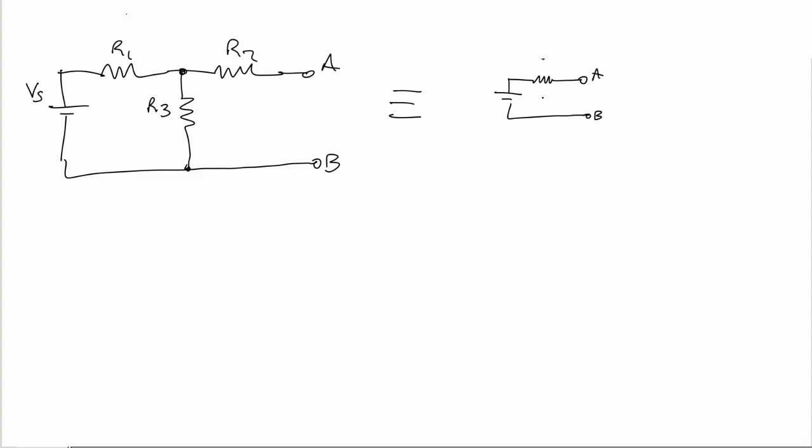What is this sort of arrangement known as? It's known as a Thevenin equivalent circuit. And this resistor, therefore, is known as RTH, the Thevenin resistance, and predictably this one's known as VTH, the Thevenin voltage. We'll describe shortly how we arrive at the values for these particular components.